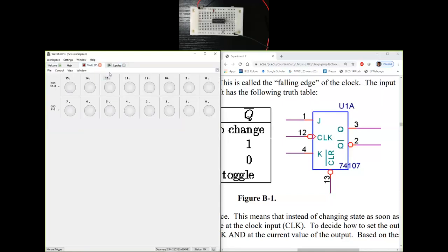But if I look at static IO, what I have is 8, 9, 10, 11 and so on. I have 0 all the way to 15, so I have 16 digital IO channels. And I could set them up as inputs or outputs depending on what my preference is. I have four of them over here.